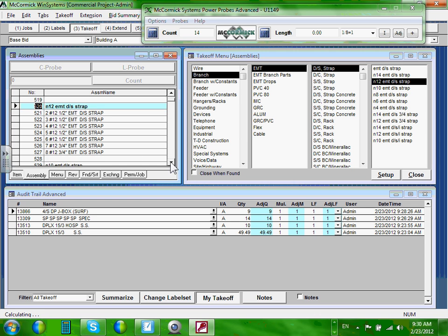It gives you all the assemblies that have been created in this system. Okay, take this. An assembly as I can go to number 12, half an inch assembly. So every time you hit this one, it will give you a pipe, EMT, number 12, as well as the connector with the pipe and the 2 wires inside it. Isn't that cool? You don't have to even worry about the pipe anymore. The pipe is coming with it. Yes, sir.